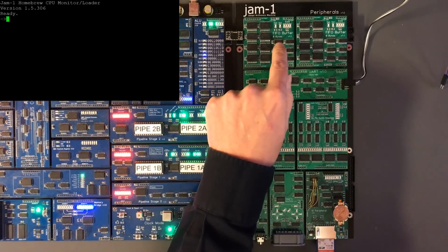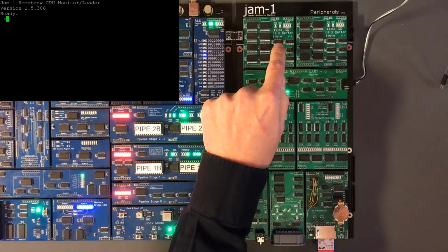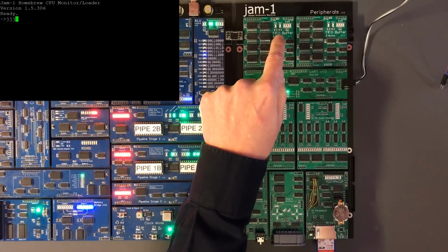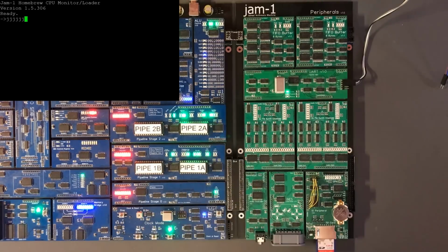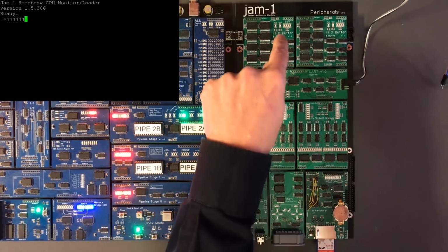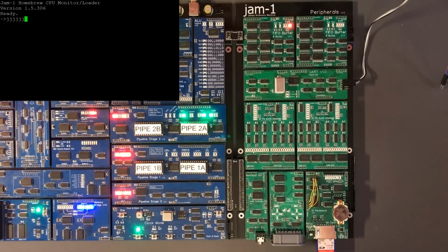If we look at the receive FIFO buffer, when we send a character, you see the lights flicker that show the characters very briefly as they are sent from the host computer and received by the UART. Now what I can do is switch the CPU into single step mode. It's not going to respond, so any characters sent are going to fill up that FIFO buffer. So, a single character, and we've got one character in the buffer.